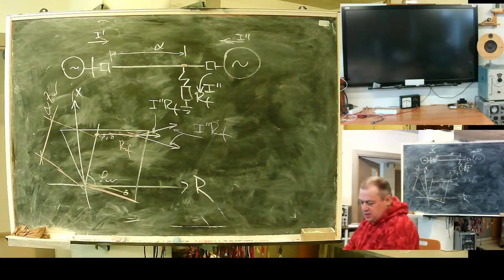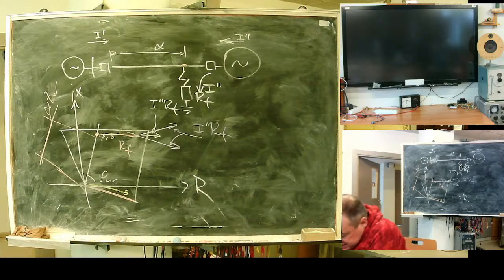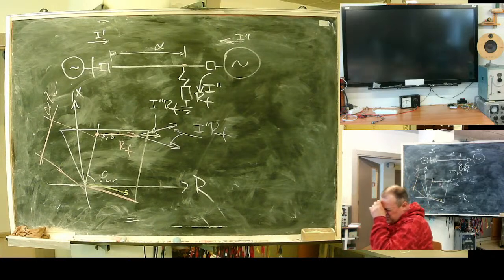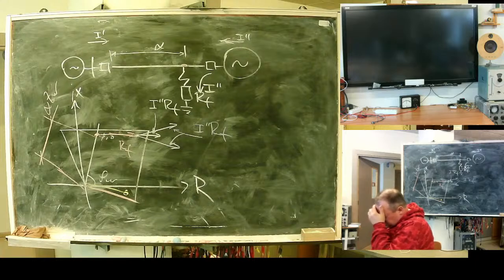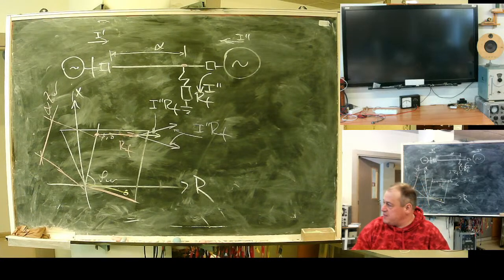Fault in voltage circuit. If one of the voltages disappears due to a fault in the secondary circuit, protection will operate firstly. To prevent this, a special circuit is implemented. It prevents protection operation in case we have zero negative sequence voltage but do not have negative sequence current. It's for faults in voltage circuits.